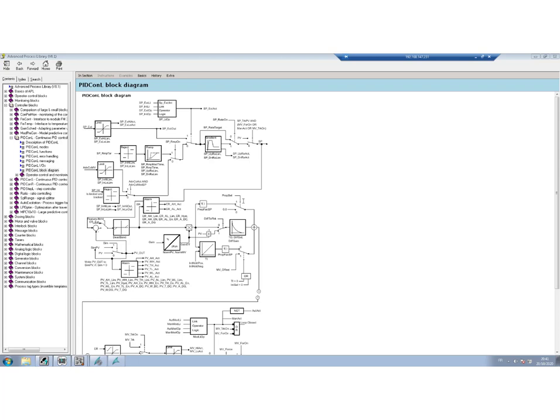You recognize over here the proportional part, the derivative part, and the integral part. Well, this parameter over here, prop fac setpoint, is really the parameter B that allows you to change this proportional kick when you have a setpoint change, right?